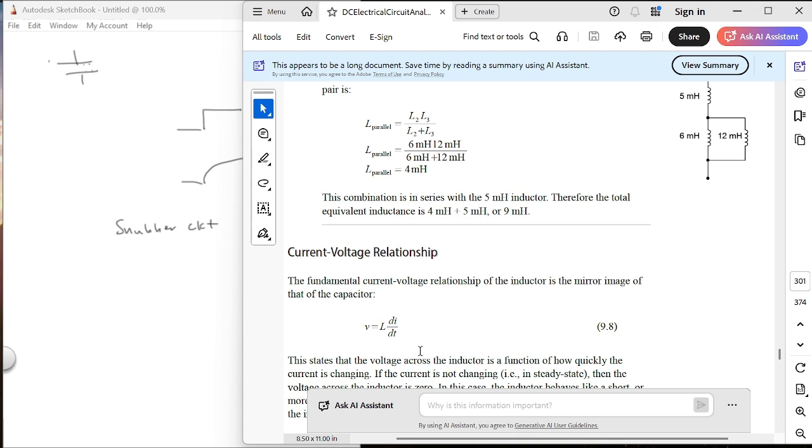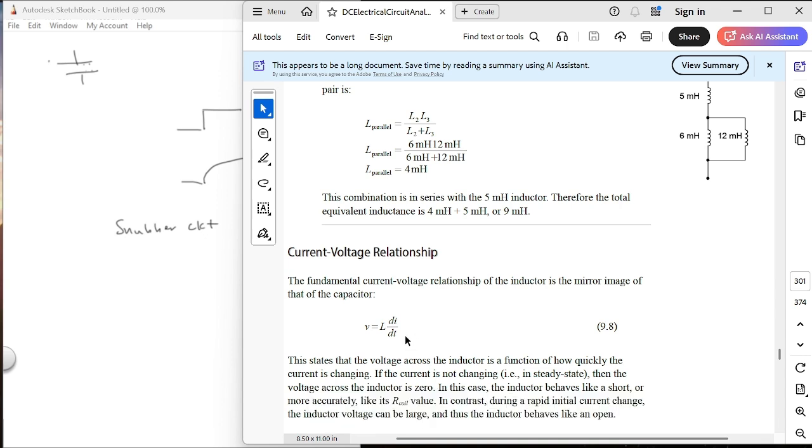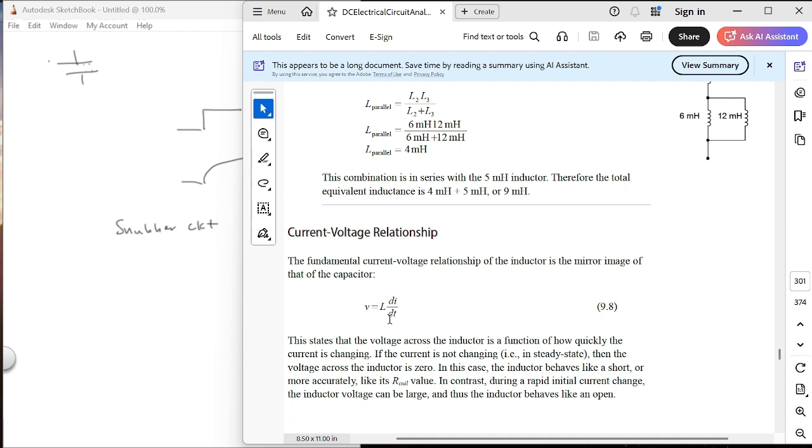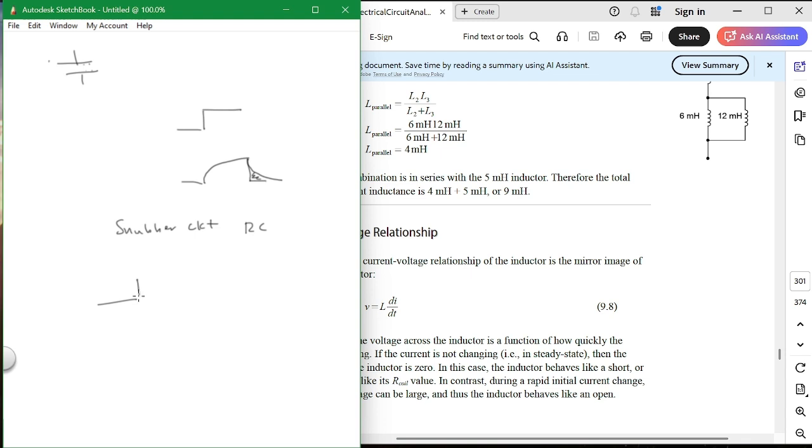And with respect to voltage and current, this is your relationship. Instead of V, sometimes we use the term E, and this means ELI. E equals L di over dt. ICE, ELI the ICEman, I equals C dV over dt, which basically says if you have an instantaneous change of current, what do you have? If the current could do this, what would voltage do?